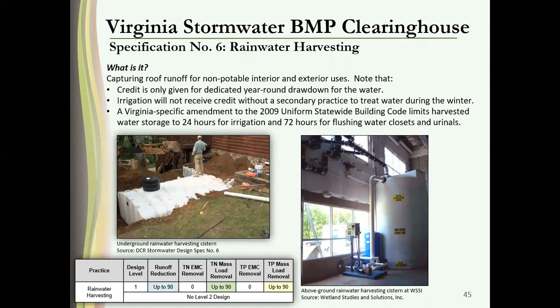Rainwater harvesting. So as I said a second ago, putting in a barrel and just getting all that water, sticking it in a big tank, it basically becomes its own settling tank. So all those captured soil particles are just going to eventually sink down to the bottom. And that's part of the reason that you can get a huge amount of treatment out of a cistern or a rain barrel. We're going to take a look at one during our tour. It's actually this one.